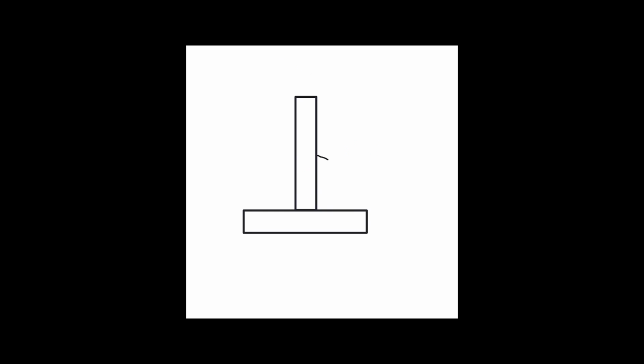After understanding what the toes of the weld are, we can then look at what the legs are. If we begin at the very start of the weld, or where the two pieces of material meet, from the very bottom of the weld all the way to where the weld ends, or the toe, the length of that distance is what's called the leg. So there's the leg for both sides of the fillet weld. There's a leg on the bottom side, and there's a leg on the top side. And effectively, when we're dealing with fillet welds, the toes of the welds and the legs of the welds work hand in hand.